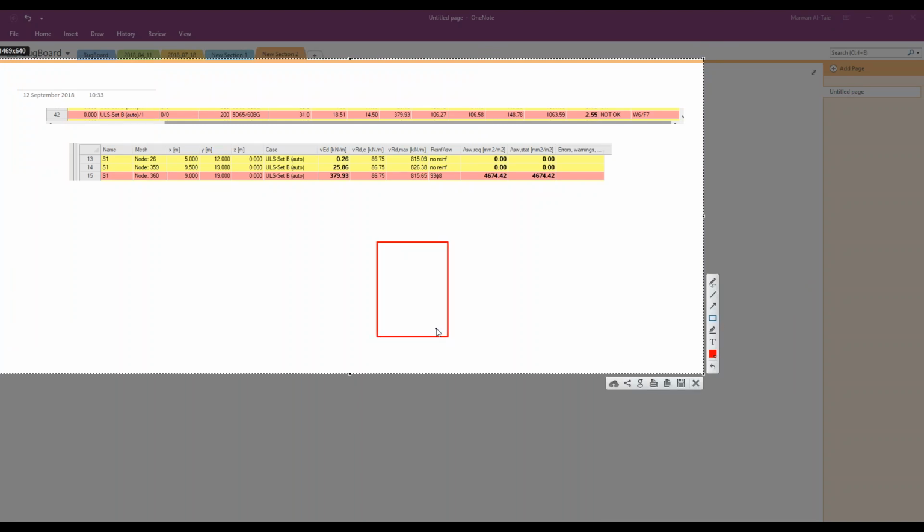Normally when we do a design, we have reinforcement somewhere and we talk about what we call effective depth. As long as there is no traditional reinforcement in my system here, I can use the full height of the cross section.